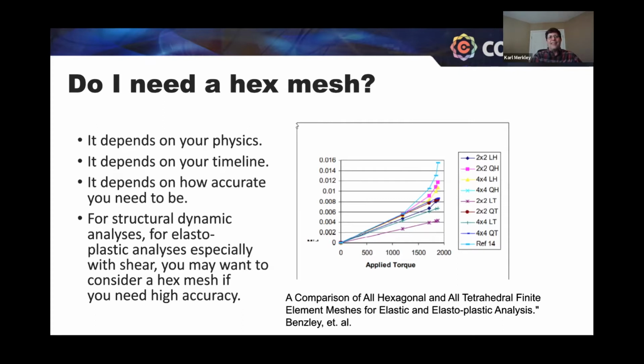This little plot at the right here. So this blue line shows a very simple problem. Take a rectangular cantilever beam, so tie it at one end, and then start to twist it. And twist it until you reach plasticity, so things start to yield. This blue line represents a closed form solution for that problem. Simple problem, we can actually do a closed form solution.